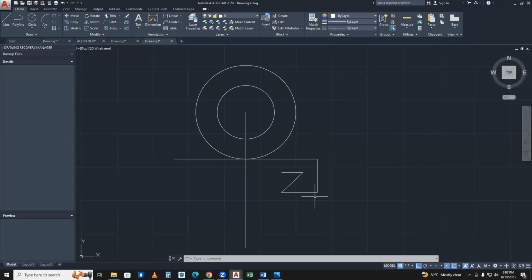It's easy. So we need the same mirror. So I'm going to choose these lines. I'm going to mirror on the left-hand side. So what is the command I do? I'll put mi, enter. So what is the axis I'm going to copy along? Along this line, I'm going to do the mirror. So I'm choosing this point. You can choose this side or this side. So we can choose anyway. Fine. So I'm choosing here. And then there's an option coming.